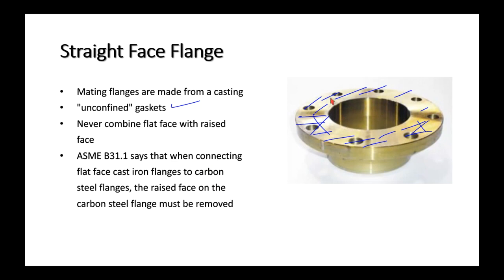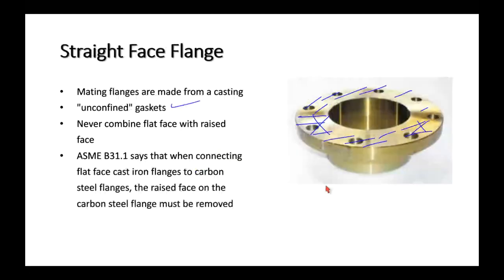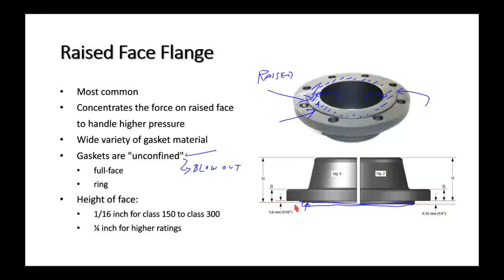Now, sometimes people will combine one of these raised faces and bolt it up to a straight face. If you want to do it, you have to actually grind off that little raised piece and make it flat.